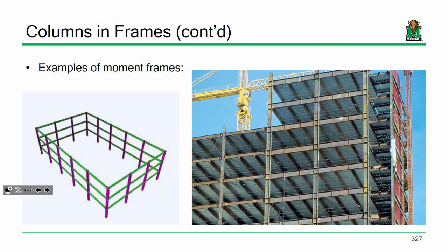Obviously the advantage of a moment frame is that there are no braces in the middle, right? So the architect and the owner, they love it. Nice open window spaces. But there are a couple of issues. First off, I kind of like this image because you can tell what's the braced frame, what's the moment frame, and what's the regular frame, I guess I would call it. Notice how right here the columns are a little deeper and the beams are a little deeper. Everybody see that? Over here, they're a little lighter.